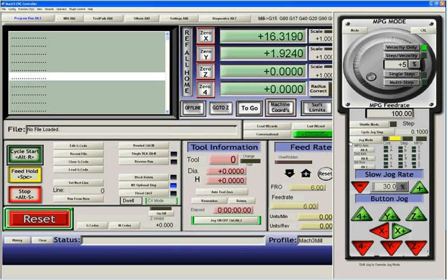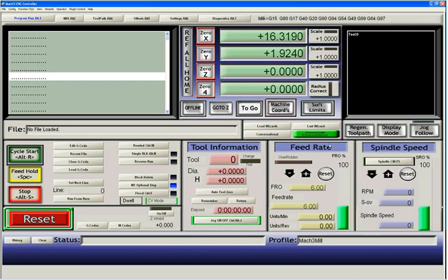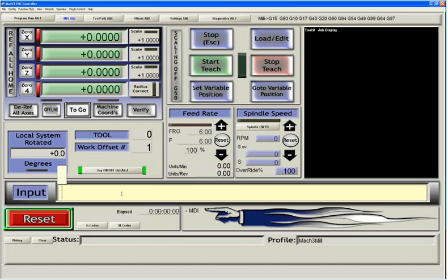The next question that often comes up is, how do I know that my axes are accurate? If I zero my X movement, and we go to the MDI screen, and we say G0 X5, you can see that the XDRO moves us to 5.000. This is correct, but many people find that their system did not move 5. In actual fact, the axis may have moved only a quarter inch, or it may have moved 10 inches.